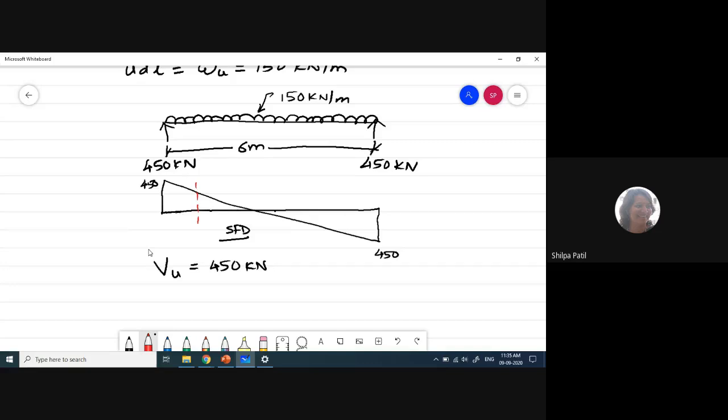Now how to reduce the amount of steel? When we provide steel in construction for any structural component, either we consider its diameter or we consider the number of bars. So either you go on reducing the diameter or you go on reducing the number of bars. In either way you can achieve the curtailment. Consider the first case, reducing the diameter of the bar. Near the support, suppose I have provided a 10 mm diameter bar. As I move towards the center, I reduce the diameter: at this section an 8 mm diameter bar, and here a 6 mm diameter bar.